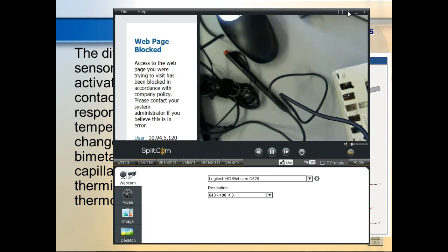So what you do is you have your meter on the temperature scale. You flip it on temperature, but you still plug it into the same inputs that you use to measure voltage. So all you're doing is measuring a voltage, but now your meter is doing what? Translating it into a temperature.